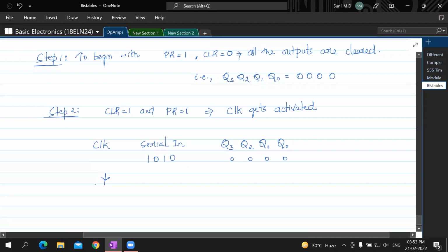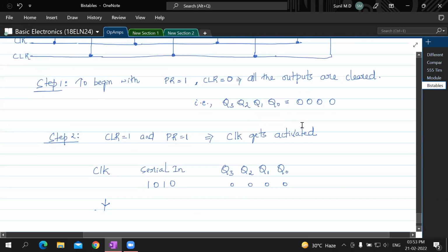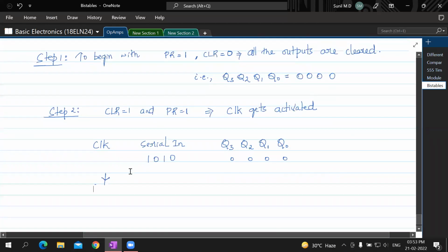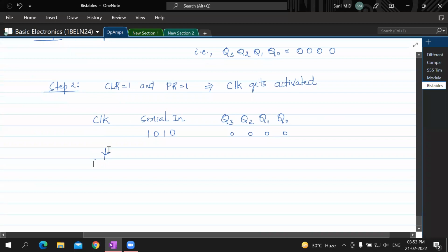why are we talking about a negative clock cycle? Because we have 0 here. We have a bubble here. That's why we talk about negative clock. So if you remove this bubble, this clock would be a positive clock. In the textbook, though he has put bubbles, he is taking positive clocks here, which is wrong. Everybody understand? So we should take the negative clock.